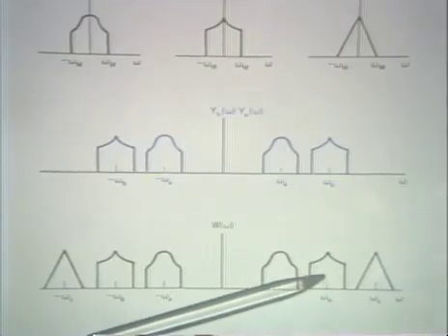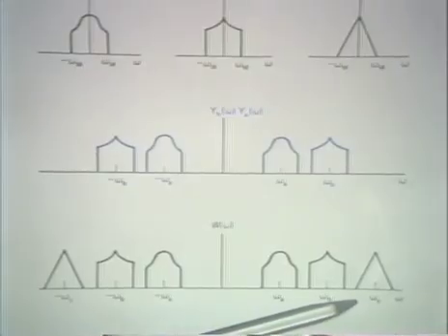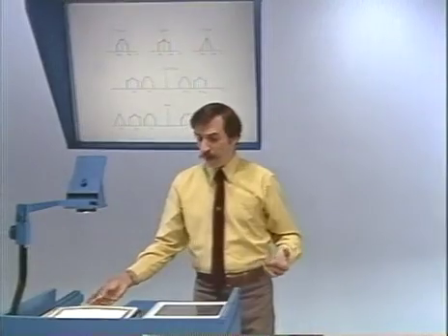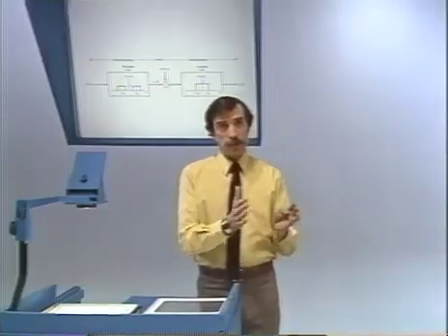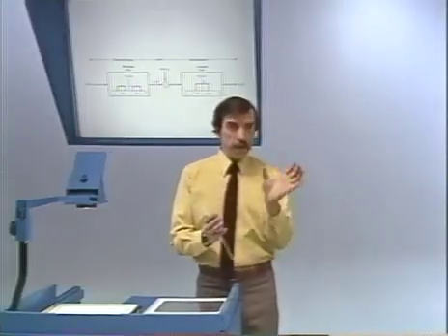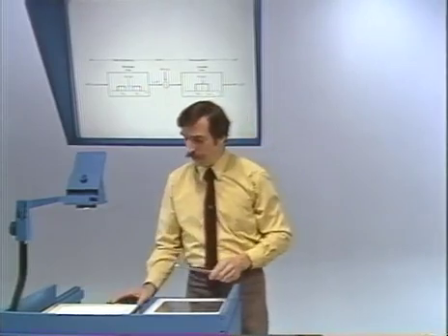And of course, we can do this not just with 3 signals, but perhaps with tens or hundreds of signals. So that's a process that is typically referred to as multiplexing. And as I've described it here, it's referred to as frequency division multiplexing. That is, dividing the frequency band into cells and plunking different signals into each one of those.